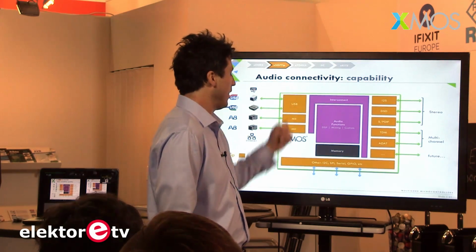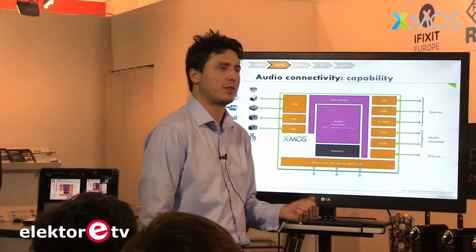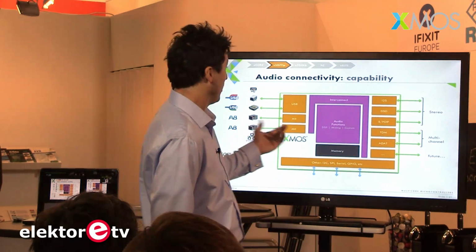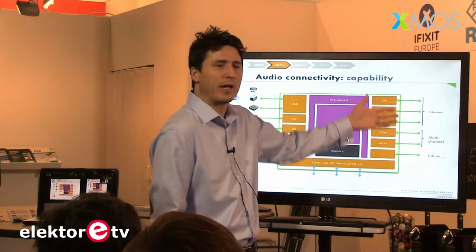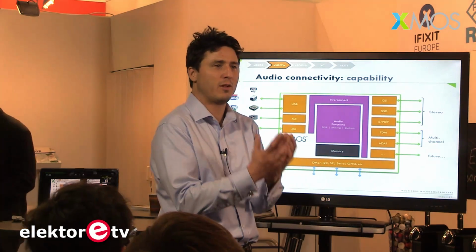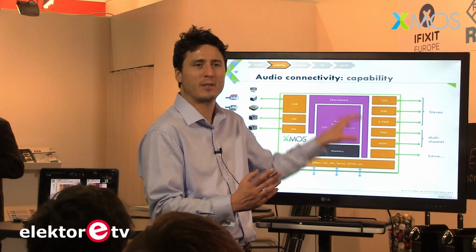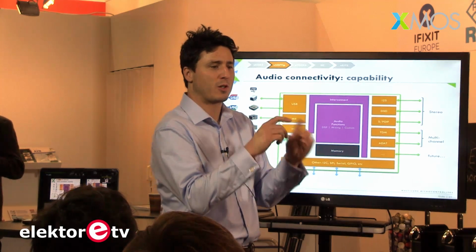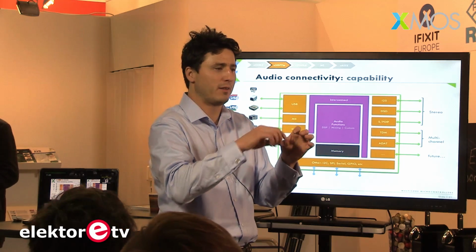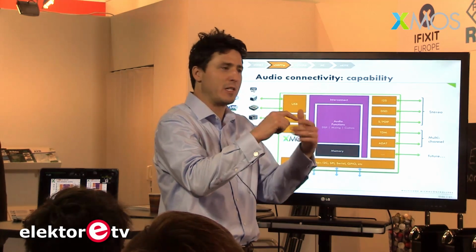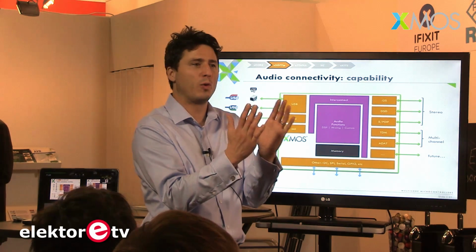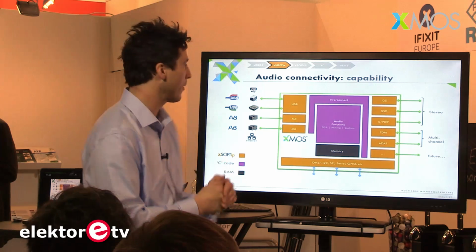And you can add DSP functions in that data path. So let's say you're streaming from USB to I2S, then it's very easy to spend an additional core to implement DSP functions. Because the cores communicate over the channels, you just put another core in, stream data into it, do the DSP and stream it on to the next core. So it gives you a very low latency deterministic data path.